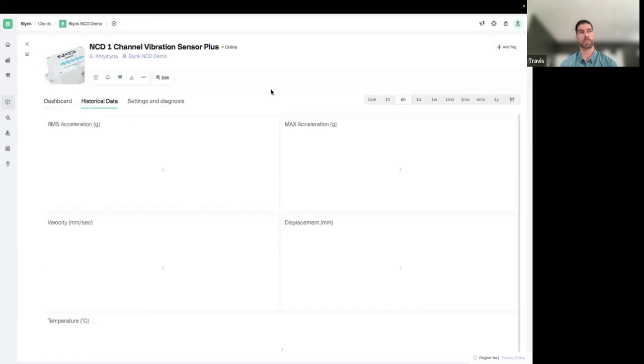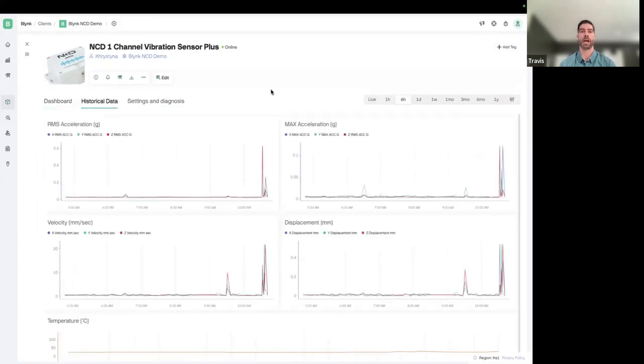But all the product pages should say how many transmissions they're rated for. So we don't rate it based on time, we rate it based on number of transmissions. So if a sensor says it's rated for 500,000 transmissions, which is pretty common amongst the enterprise line, you can multiply that by your report interval and basically calculate your estimated battery life.